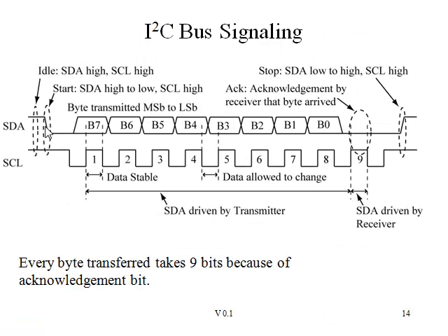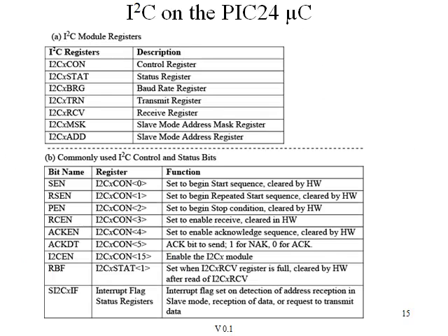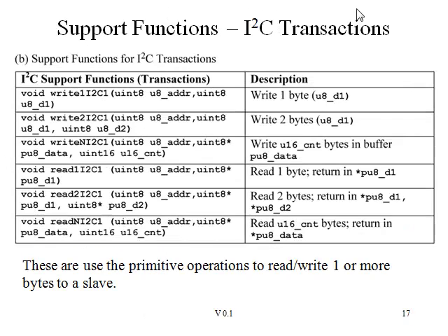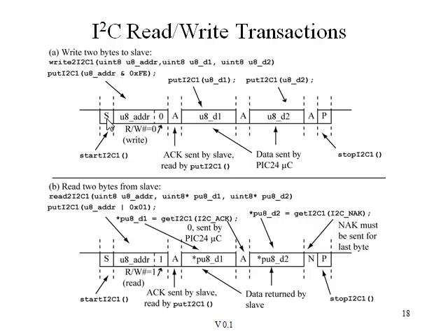The protocol always begins with a start bit. It consists of 8 data bits followed by an acknowledge, and a transmission is ended by a stop bit. There are 2 types of transactions: a write transaction, a start, the address with the write bit cleared to a 0, data to be written, then a stop. A read transaction, beginning with a start bit, the read address with 1 for the read-write bit, data read and an acknowledge to request more data by the master, data from the slave, and no acknowledge to conclude the transaction, a stop from the master.